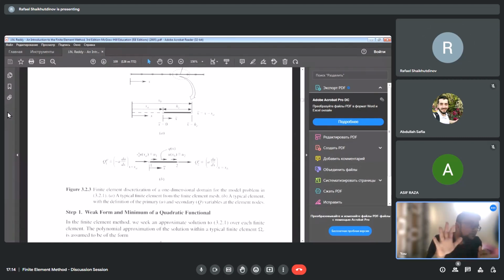As I told you, a sign convention should be only in one direction, right? Yes. Now this Q2 value, it is exactly a du by dx. But for Q1, in reality it is opposing the reaction. It should be on the negative side, right? But our sign convention is to take everything along the positive side. That's why we are taking minus a du by dx at the left hand side.